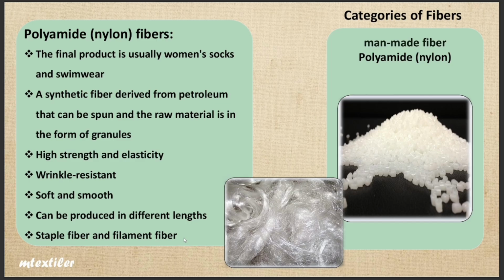Two commonly used types of polyamide are nylon 6 and nylon 66. The difference in their chemical structures results in two distinct types of polyamide fiber. Nylon 6, with fewer crystalline regions, is softer than nylon 66, which has more crystalline regions. Properties such as melting point, tensile strength, dyeability, and moisture absorption depend on the level of crystallinity.